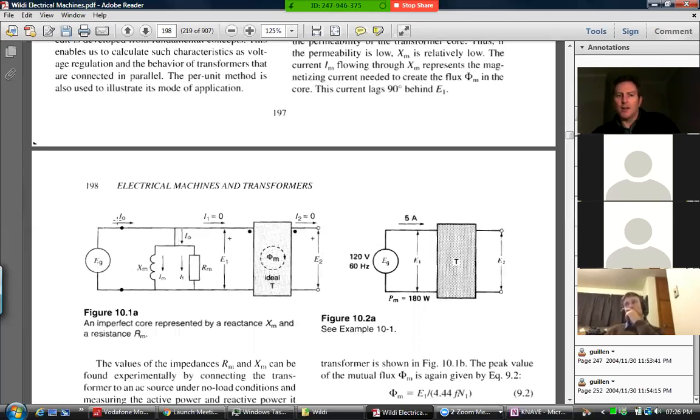in the primary side through these parameters represented as X and R. And those are the parameters that are there for the setting up of this alternating flux. So this would be the no load scenario. No load meaning we're not supplying any external resistor on the secondary side, but we still do have a bit of power wastage. There is some current that gets pulled from the supplier.